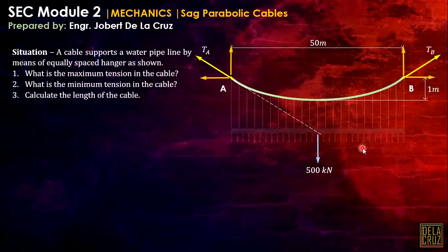One of the principles here is that the line of action at A and the line of action at B should always meet at the point where the resultant force of the uniformly distributed load acts. They always meet there, to maintain equilibrium.